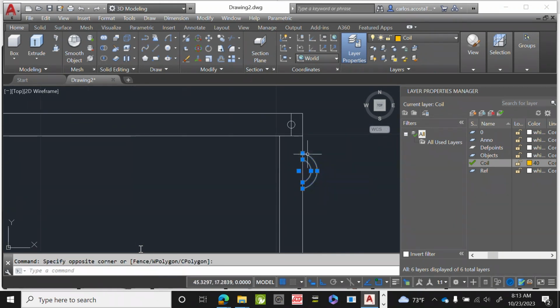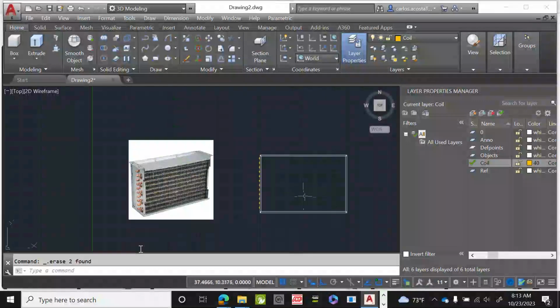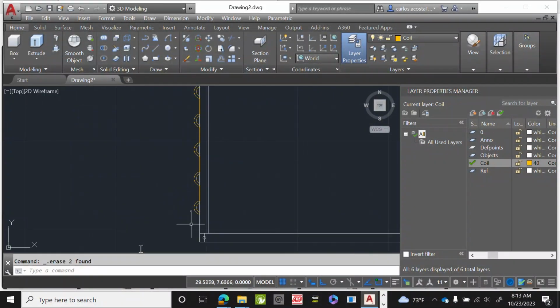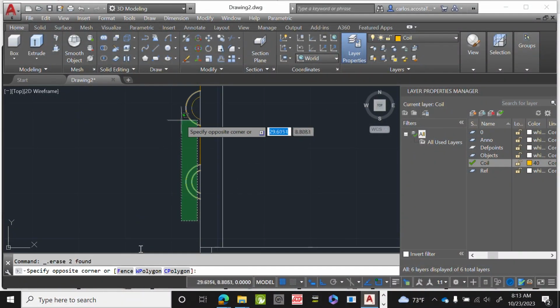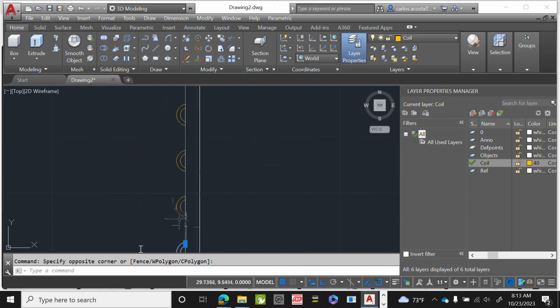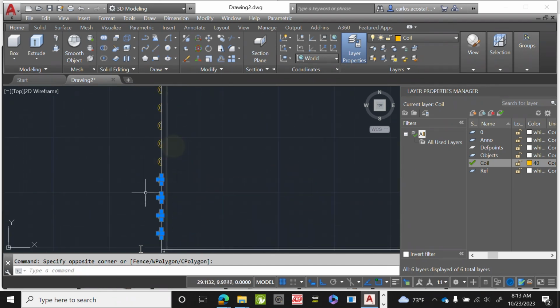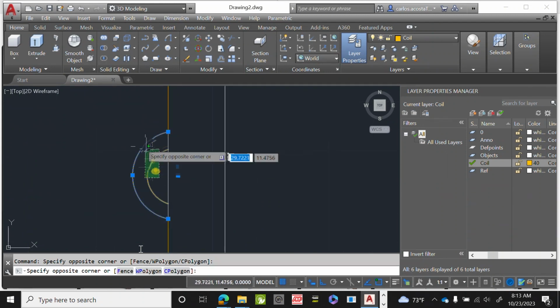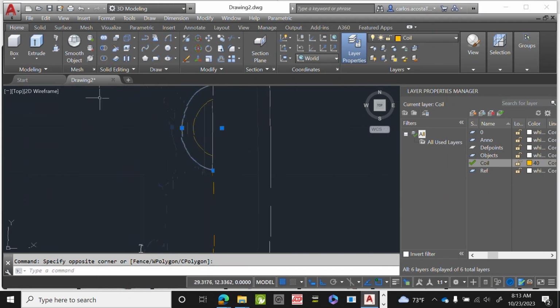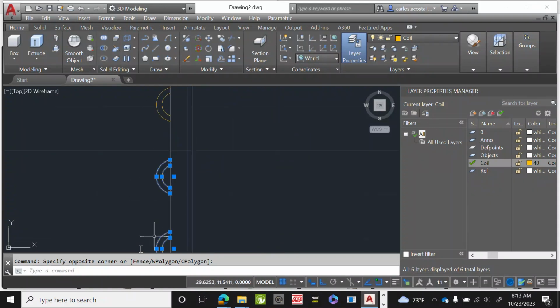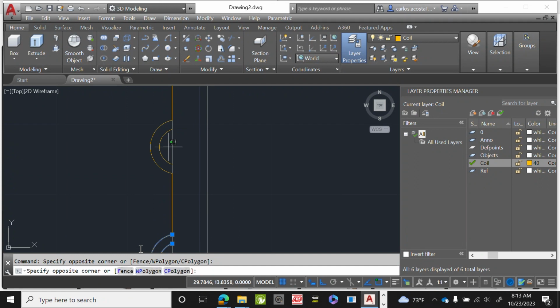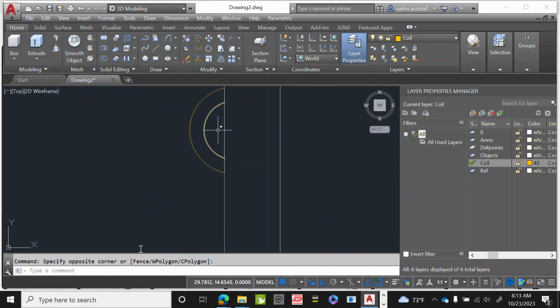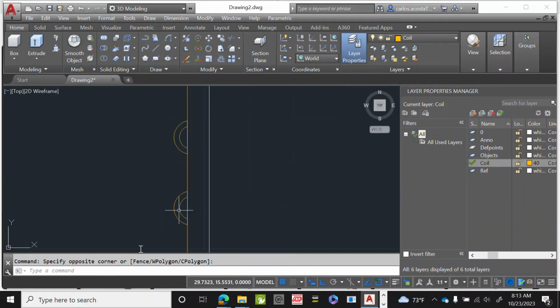Actually, the mirror option was the best operation right here because we simply have to select all those objects in a mirror. Will make sure that we have the same distance. Problem with path, polar or an array on the path is then we have to specify this distance, and it's not going to be exactly the same because we're not following a drawing.